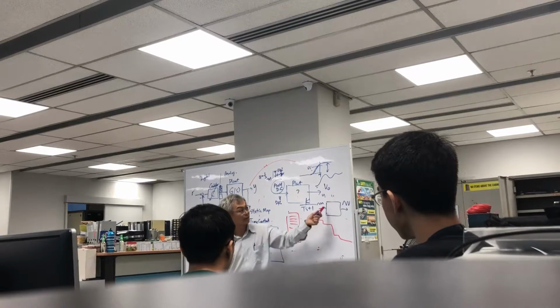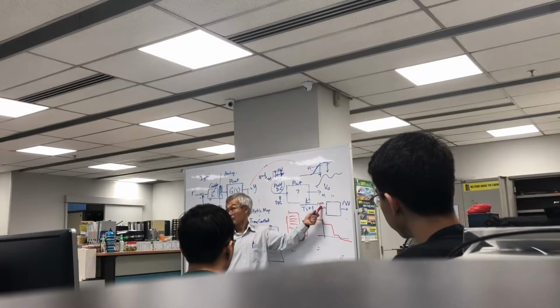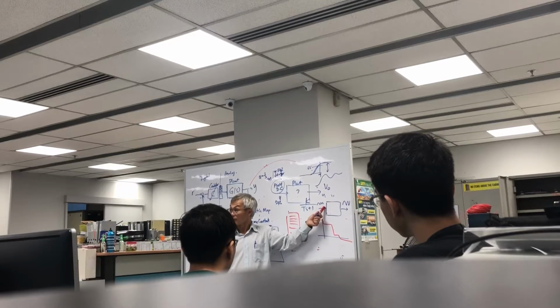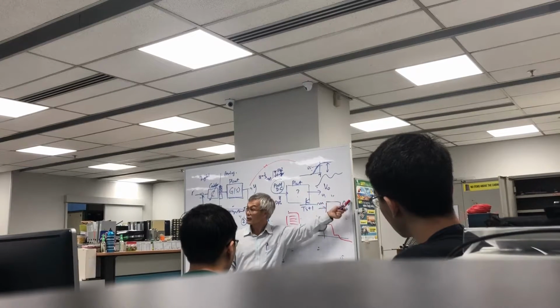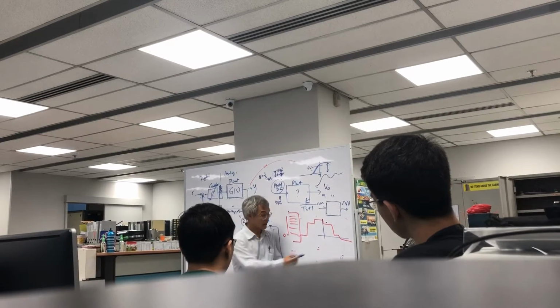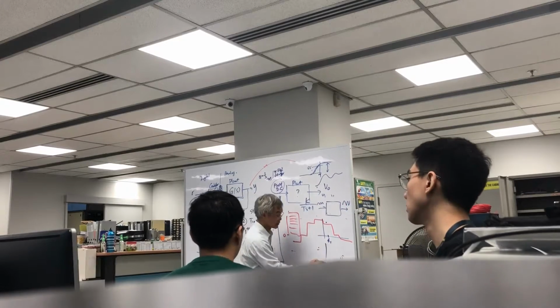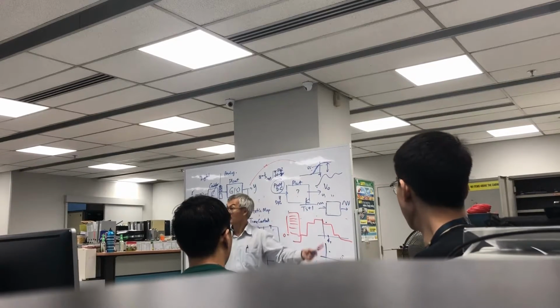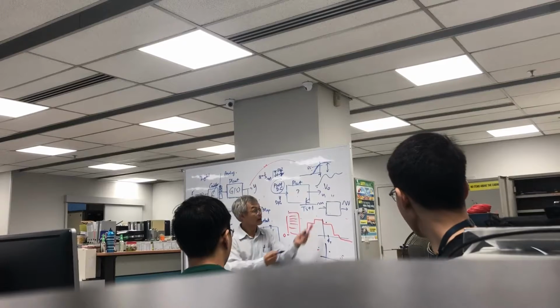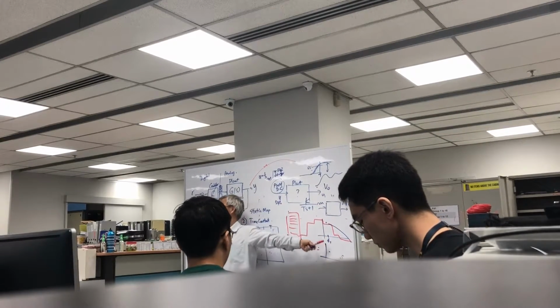So in principle, to work out the frequency response you send in a sine wave at a particular frequency, look at the gain, you get a point at this frequency. You look at the phase difference, you get another point. That's your magnitude plot, that's your phase plot. Then you change the frequency, you get this. This is a Bode plot.